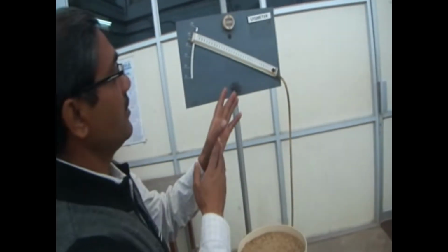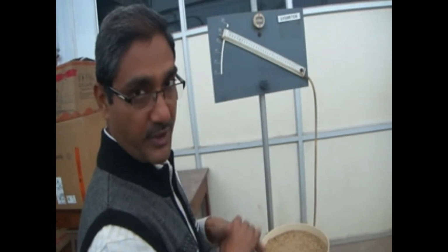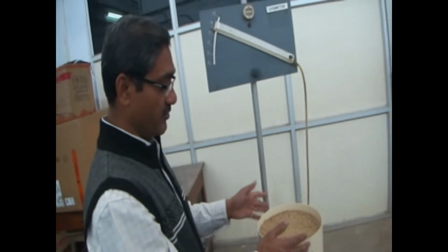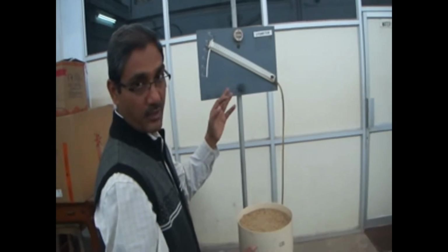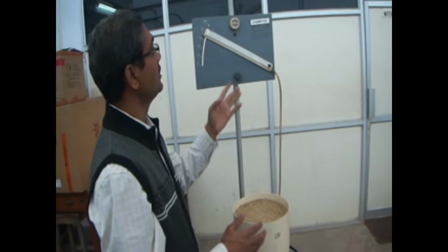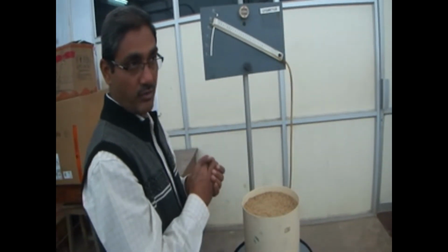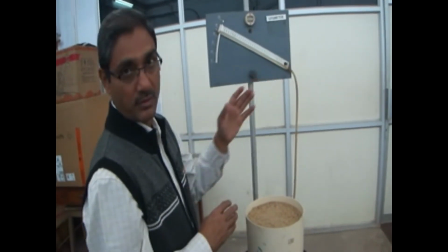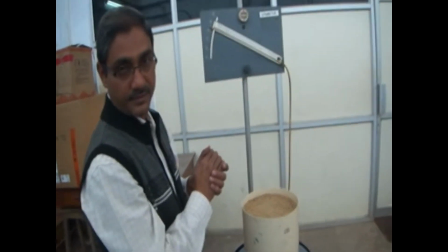So this is the idea to find out the calibration curve of a real setup of lysimeter, so that the moment we have measured the weight of the lysimeter, because it's a weighing type, we can find out the content of soil moisture that has been used as evapotranspiration. I will give you observations for other angles, so you can find out the characteristic curve or calibration curve, and also find out the rate of change, that is tan theta. That's all.